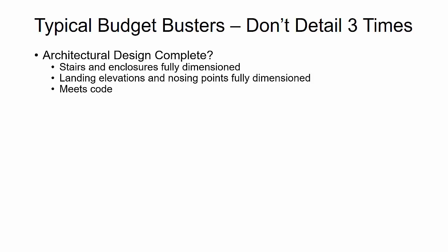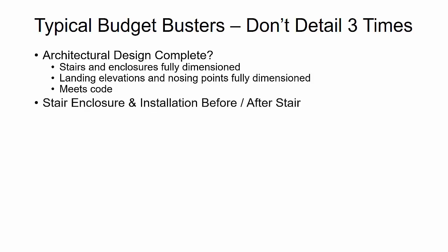Now, what comes with that, though, is that there's more detailing involved, and you want to detail in steps, first working out the geometry and the dimensions before you fully dimension and make the shop drawings on your stairs. And that's part of what we're going to show here. The next thing you need to understand is what's the stair enclosure system, and does that affect the stair being installed before the enclosure is put in or after?